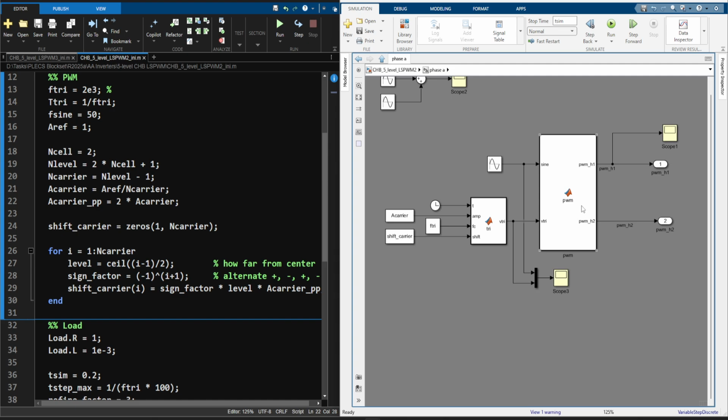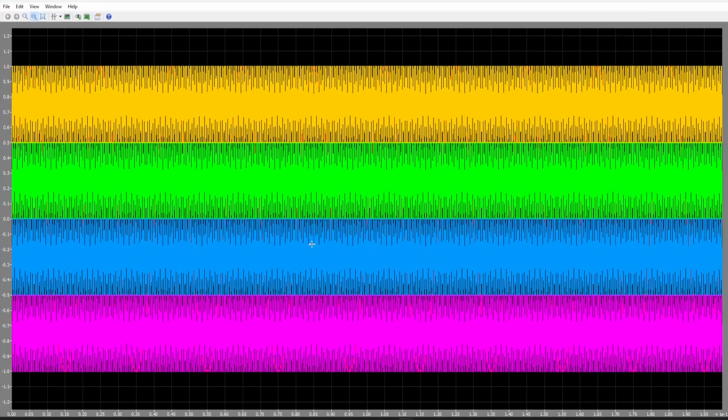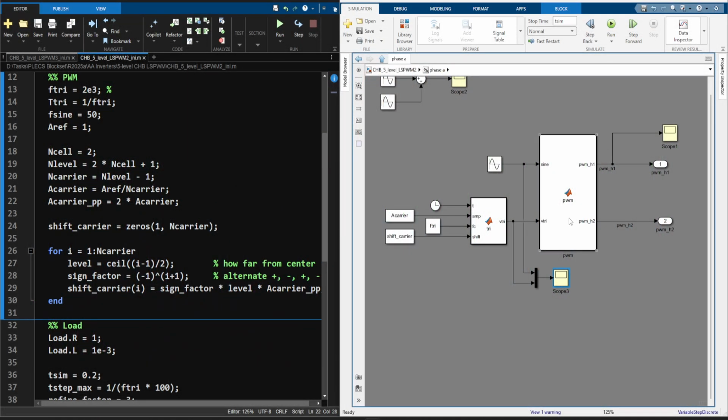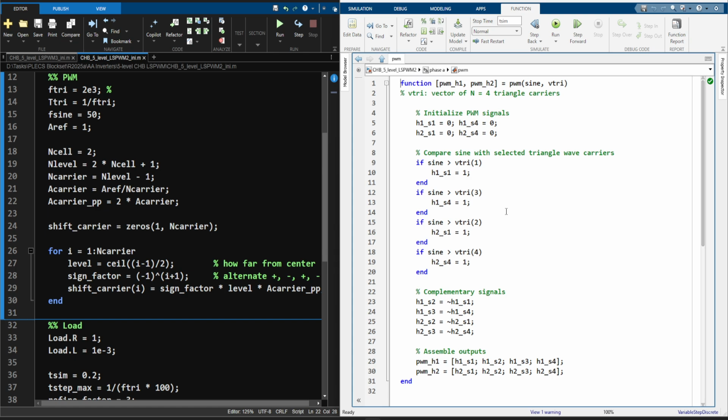And inside the PWM generation, if you remember, we need to have our carrier waves and the sinusoidal wave, which is, again, let's see it here. So we have to compare this reference wave to our carrier waves, and depending on where we are, we produce the gate signals of the IGBTs accordingly. And this is done exactly here.